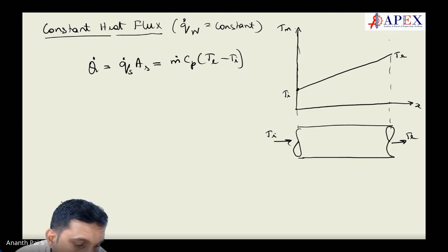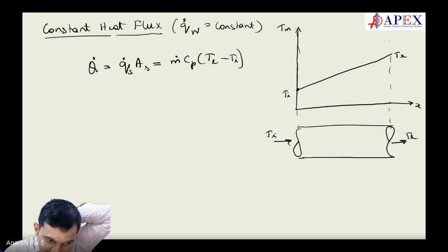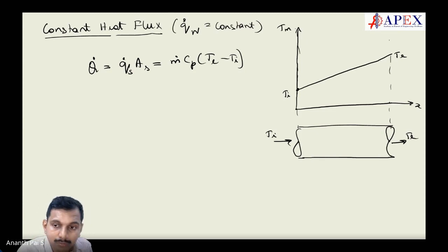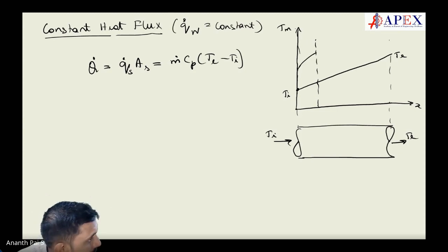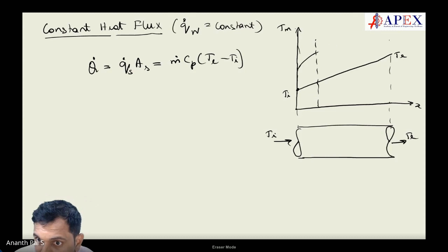We have to keep constant heat flux. So if this is a hot fluid, okay, sorry, if I consider to maintain the same heat transfer coefficient, what should I do? Suppose I have the entrance region. If you have to maintain constant heat flux, then heat transfer coefficient is more here. So I have to maintain wall temperature in such a way that the difference here is the same.